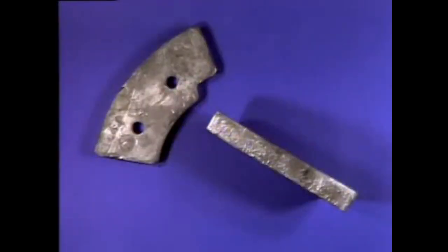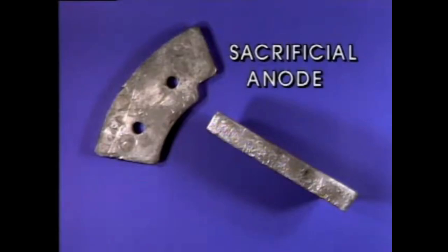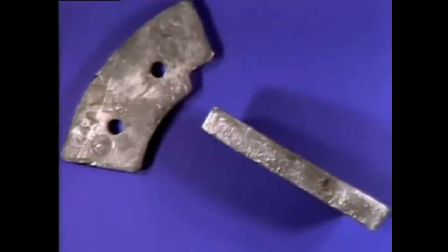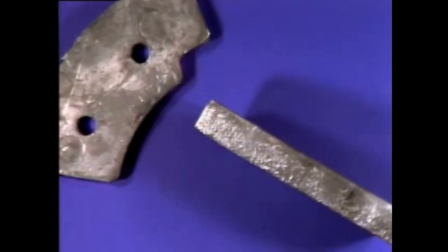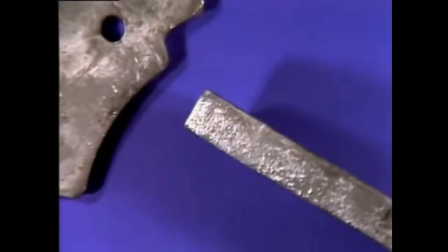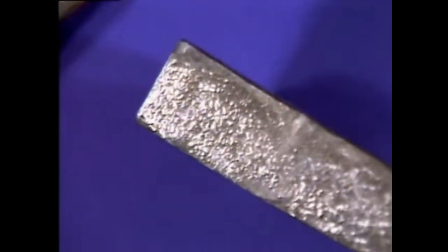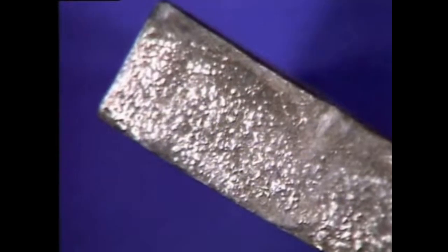To prevent leaks in some applications, the process fluids pass through filters or strainers to remove impurities that can erode the tube metal. Also, chemicals may be added to the fluids to control corrosion. Another method of controlling corrosion involves using a device called a sacrificial anode. When a sacrificial anode is used, impurities in water tend to react more readily with the anode than with the metal of the heat exchanger. So the sacrificial anode corrodes while the heat exchanger is less affected. Heat exchangers that are used with water often have sacrificial anodes made up of zinc plates mounted inside.